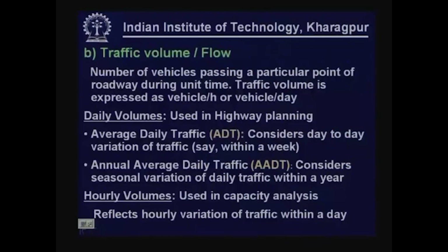And this traffic volume even takes into consideration the seasonal variation of traffic. Sometimes we find traffic may be more in winter, less maybe during the rainy season, moderate maybe during the summer. So, all sorts of seasonal variations are also reflected in terms of AADT measurement, but ADT does not reflect the change of traffic from one season to another.